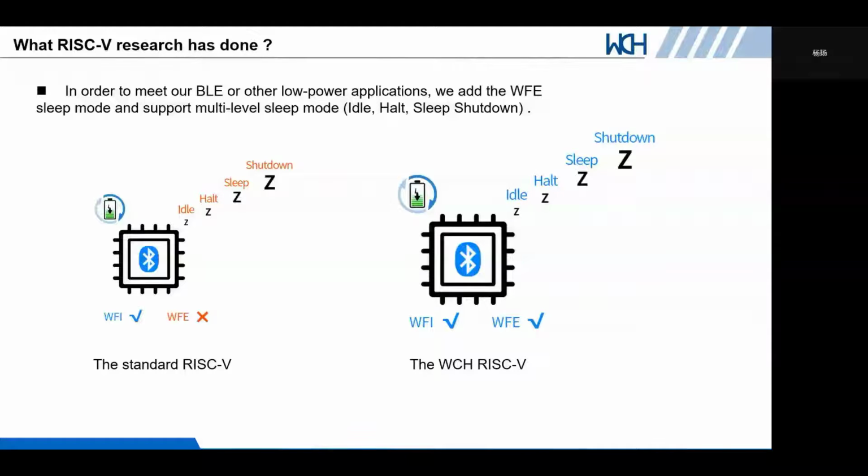However, when porting to RISC-V applications, it is found that the existing RISC-V instruction set does not support WFE sleep mode, and the application breadth is relatively limited because compared to WFE, WFI wake-up sources are limited, and at the same time, it is more demanding for real-time requirements.